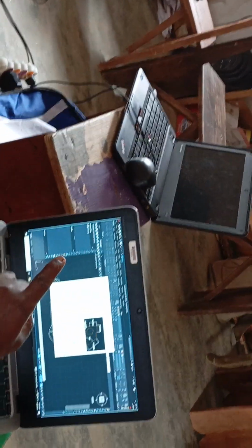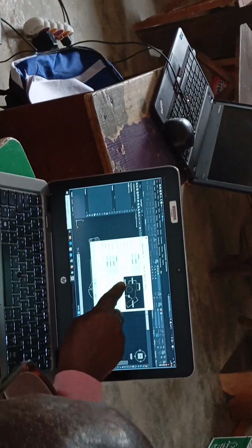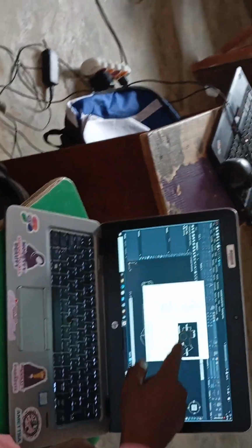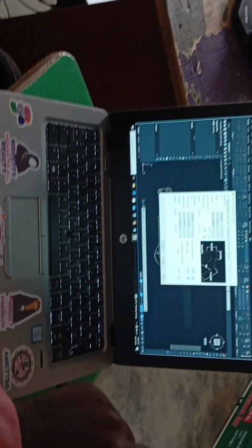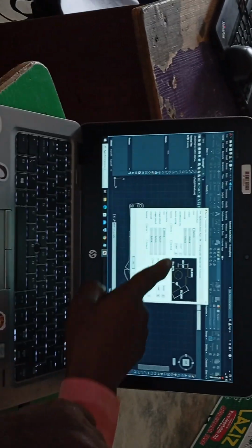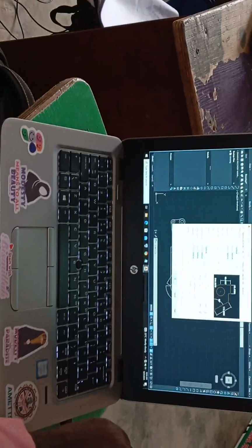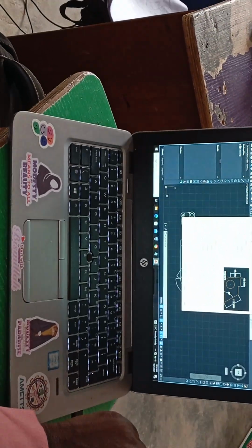Is it 10 for the text? Let's put 5. Enter. You can see that my extension line has shifted from the body of the drawing by 5. So what other parameters do we have there? Extend beyond dimension line. Let me give it 4. Not necessarily a long extension. Can you see it coming out a bit? Then I've already done that, that's on lines. Are you with me? Yes.